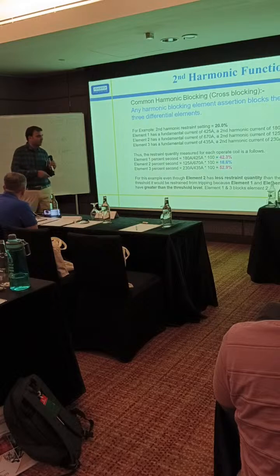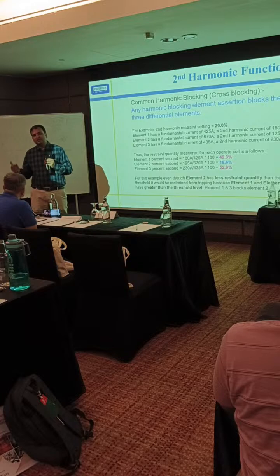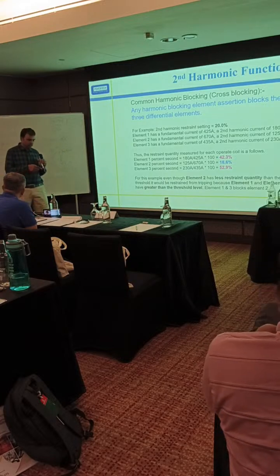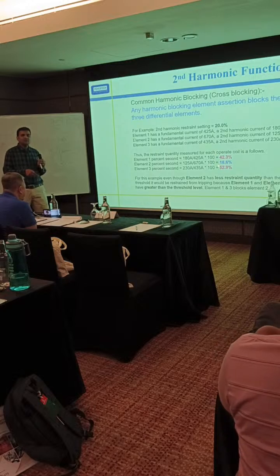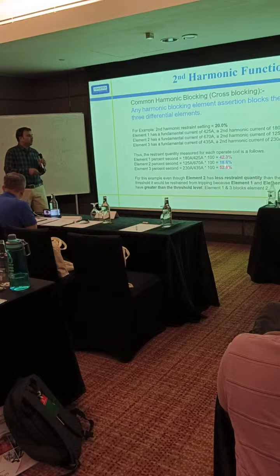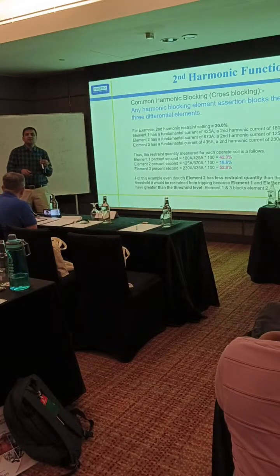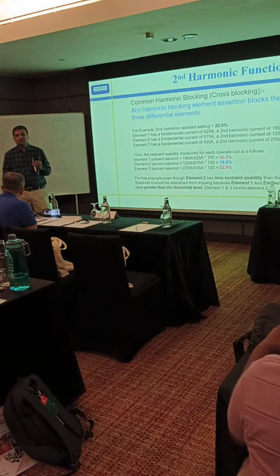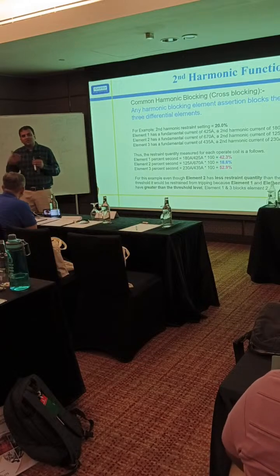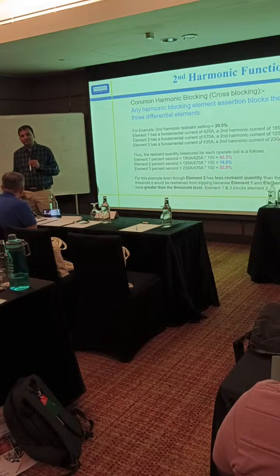But I have seen practically in one case there was an interturn fault condition. In that case, it was in operating region, and the fault was there, but due to other two elements blocking, the relay didn't trip, or it took a long time. So in most cases it is useful, but sometimes it creates problems as well.